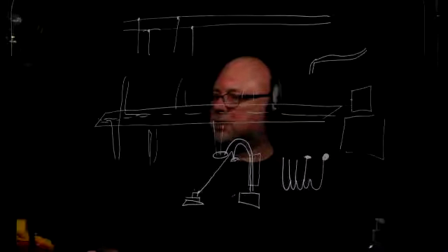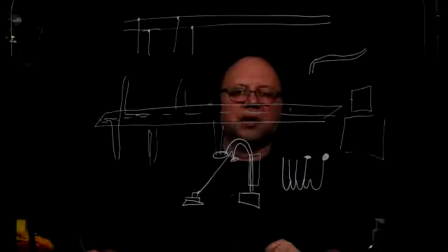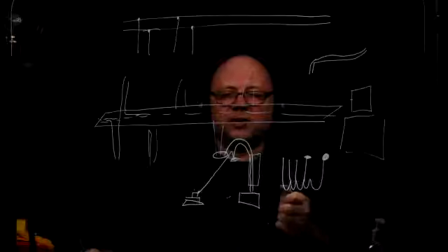Oh, there's a question here. Stephen. All right. How exactly can that damage the speaker? You mean if you have a 10-watt amplifier and a 100-watt speaker, yeah, okay. So with the weak amplifier, you can crank it up and it's not going to sound too loud to your ear, but the signal might be distorted.